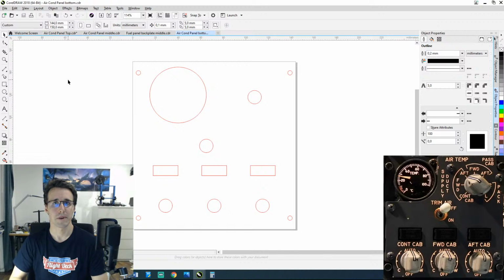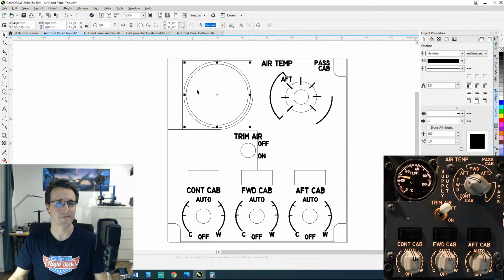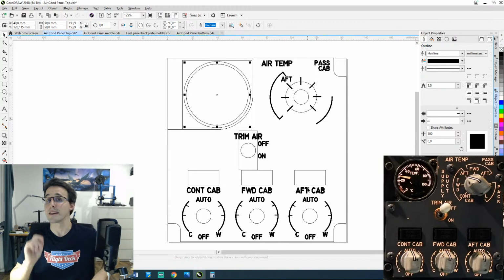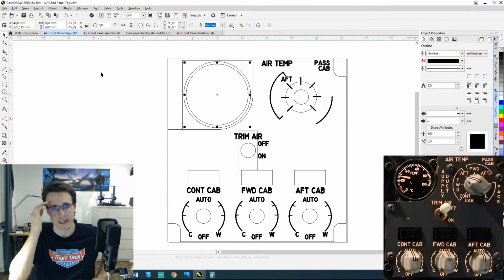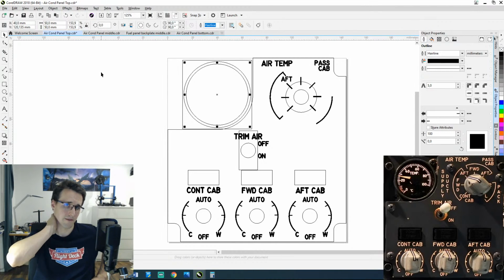This can be achieved by making a special PCB with dedicated LEDs behind. Here you can see this behind every text. Then here and here there would sit some small LEDs. This is how I think the real cockpit panels are made. But this is much work, and you have to solder every LED separately. Yeah, it wasn't the way I have chosen.